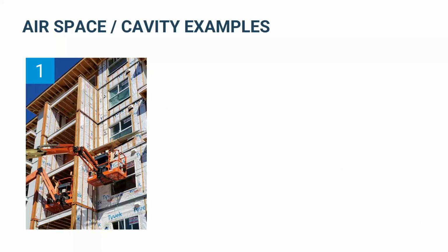This one's pretty typical. You've got your house wrap there, and you've just got vertical wood strapping or furring. Very common in multifamily construction. Starting to see it more in single-family homes now. But that's a great way to get that cavity, just continuous vertical cavities through the wall there. You've got flashings at each floor line and window heads to kind of break that up.